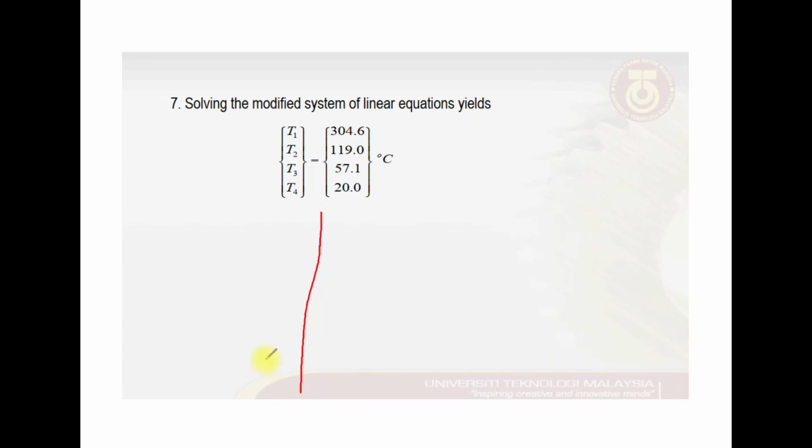So this is the temperature at each node point after we solve the equations simultaneously. Then from there let's say I take the x-axis as the node numbering. So node number 1 is located there, node number 2, node number 3, and node number 4. From there I can plot the temperature distribution across the plane wall that was developed based on layers of 3 different materials. This is not to scale.